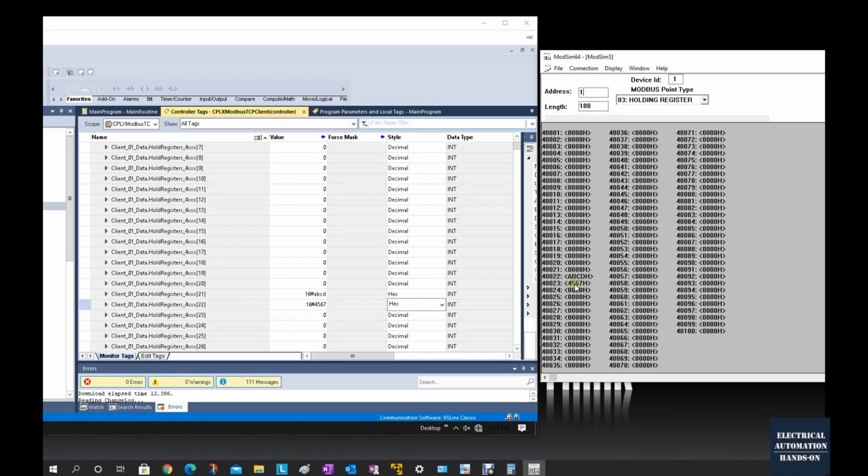But here is one thing. We wanted to send to Modbus 4021, but it got a 1 off here. We can temporarily park that: the data is received correctly, but the address is 1 off. Let's double verify the reading data buffer. From the number 1 here, let's double click this 4000. Here we can type in the hex value, for example 3344.